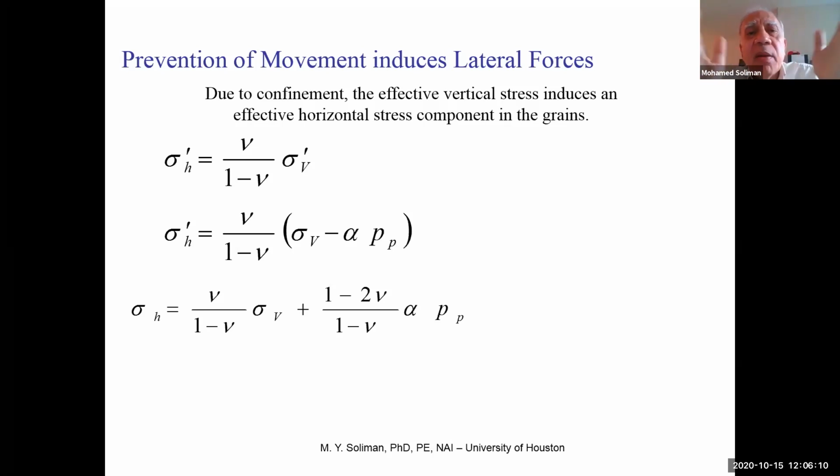Basically, all you're saying is that when we calculate Poisson's ratio, we're saying it's unconfined, and we calculate how much lateral strain you have. But if that rock, where you're applying stress, is part of a huge formation, then it doesn't have room to expand. Then it's applying stress.